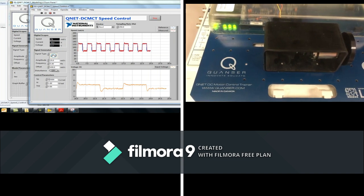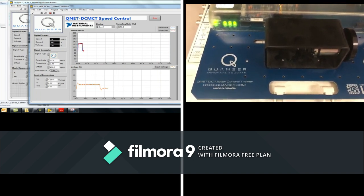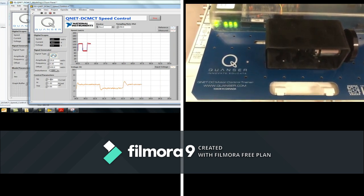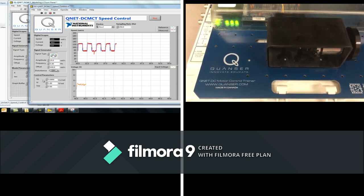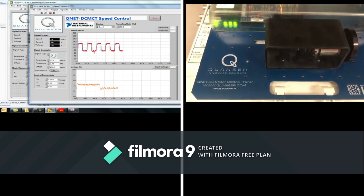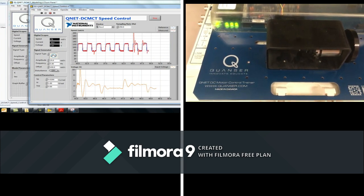So next time we will learn how to control the P parameter and I parameter, proportional and integral gains, in order to have a perfect match. For example, if instead of 0.5 I make it 0.9, we will find that I have deleted that overshoot. That means if we increase the KP, the value of overshoot will decrease. If I make it 0.2, you find that we have high overshoot. So we will do the speed control next time.